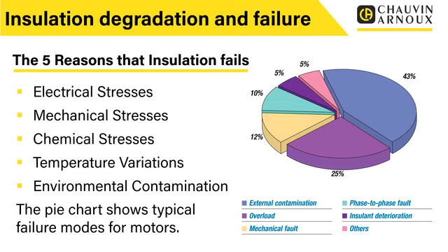Stress is also linked to temperature variations. So again, we can have things like thermal cycling. When insulation heats up and cools down, it can cause it to degrade. But we can also get heating within the motor itself. So maybe if the motor's overloaded, again, this is another form of electrical stress, but the temperature effect of that can actually affect the insulation. So there are a lot of reasons for temperature-related stress on insulation.